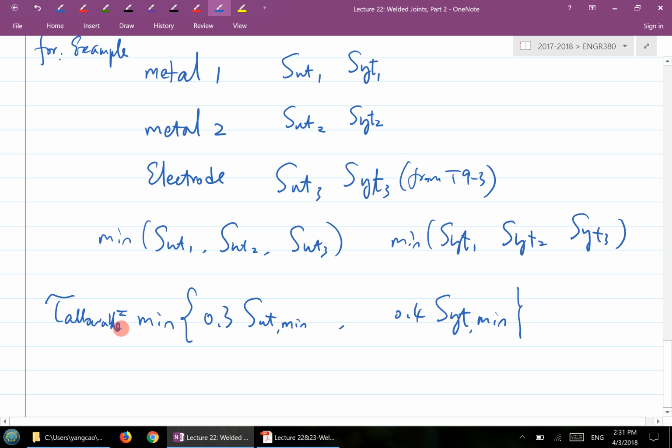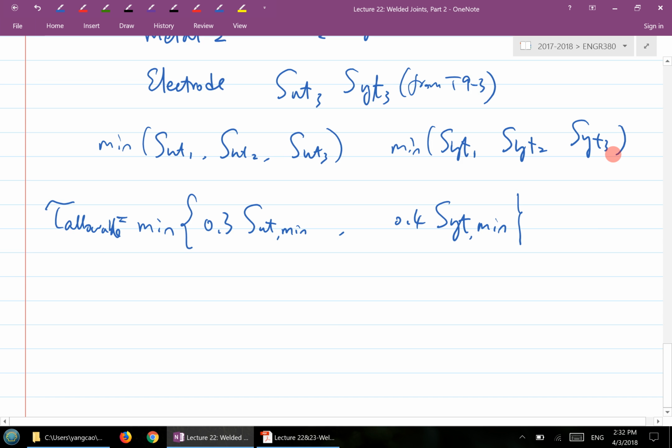So you calculate the actual stress based on case 1 and case 2, and then you calculate the allowable stress based on this scenario. Then you compare these 2, and you'll be able to determine whether you have a safe condition or not. So that's the process here. You have a stress, you have a strength, and that's it. Now for design, there are 2 different cases.